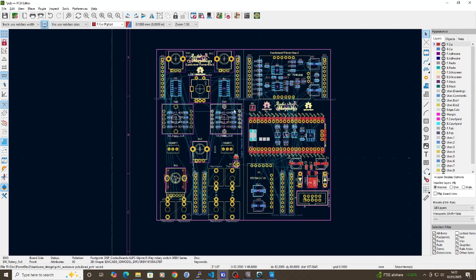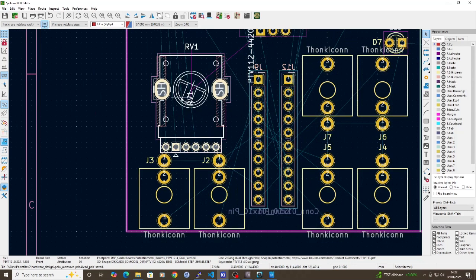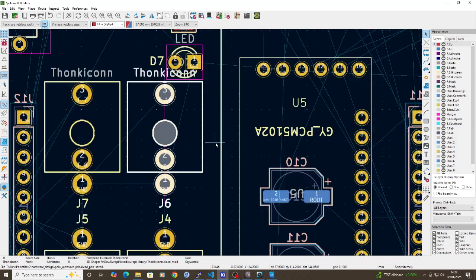Well, obviously I've changed one to an 8-way switch from a 4-way switch, this one here, and I've rotated them by 90 degrees. I've also rotated the input volume control by 180 degrees, and because of its physical pad footprint layout, I've had to move it up the board by 1mm. So I've moved the input and output clock sockets up by 1mm.